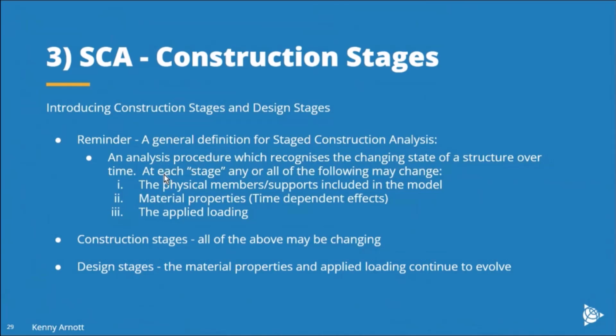So just another reminder about what happens in stage construction analysis. It's an analysis procedure where any or all of these things may change: the physical members, supports, the model, the material properties, the applied loading. So during the construction stages, all of these things are changing. During the design stages, the model is complete. So the first item is not changing, but the material properties and the applied loading can continue to evolve.